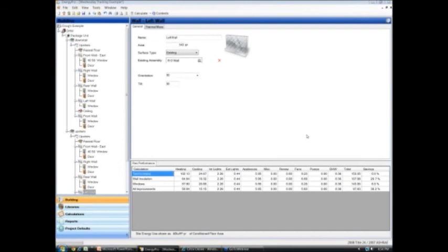So you started at 25% duct leakage and only got down to 20. That second model would show in the alternatives tab that the final duct leakage is 20%, and we would calculate the savings based on that, and that's what we would use to determine the actual rebate calculation.